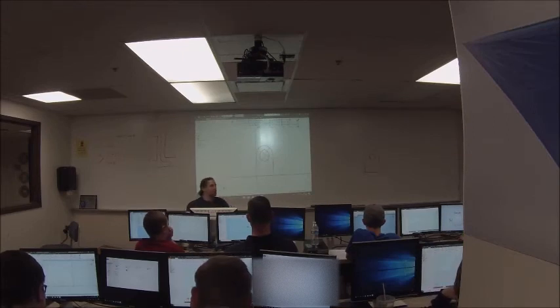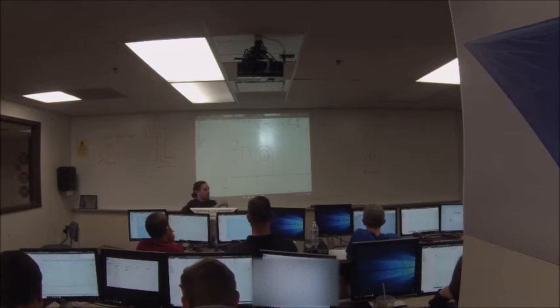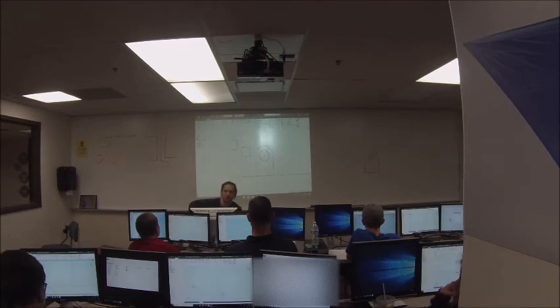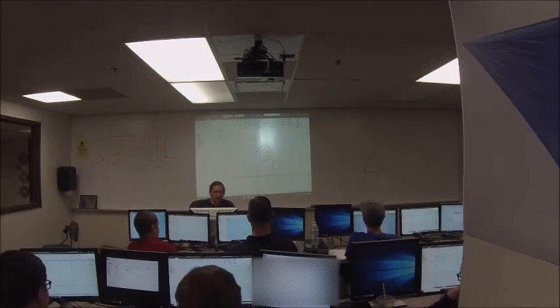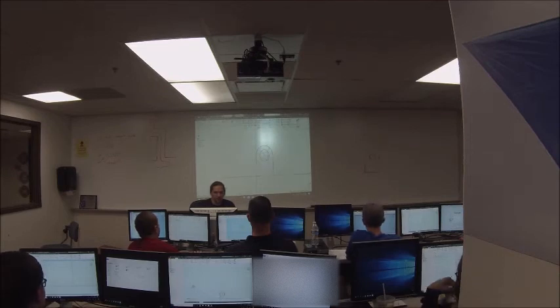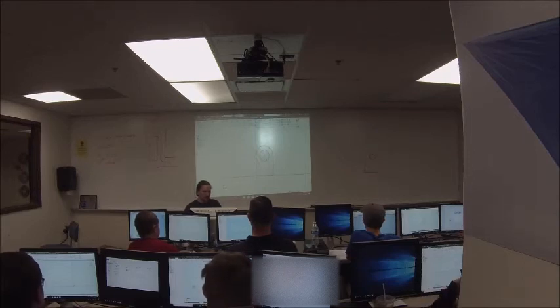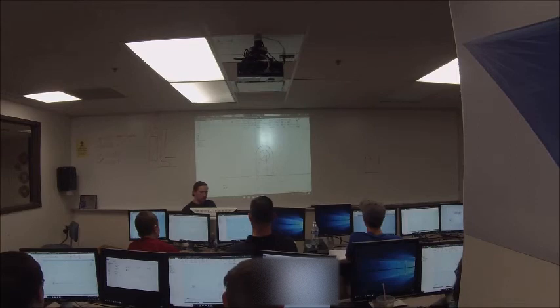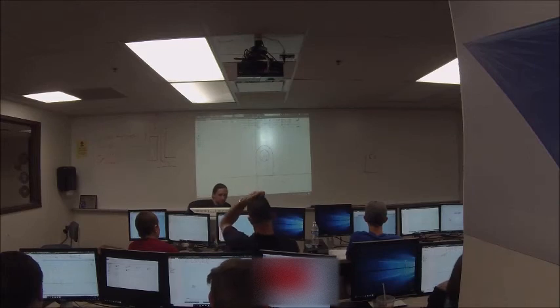Okay, so fillet basically takes a sharp corner and automatically rounds it. It places a little arc there in the corner of a specified radius, and it attaches to geometry automatically. So if I click the fillet tool, I get this little box that pops up, and I can type in a diameter. I want a 1/4 inch, which is 0.25 inches. Then I can click on one line, and I can click on the other line, and you can see when I hover over it, it shows me a little green highlight. I can fillet this corner, I can fillet this corner. So I can click the other line, bam, makes a little fillet. If I want to fillet the other corner, I can click this line and click this line, and it makes another fillet. Then I can just hit escape when I'm done.